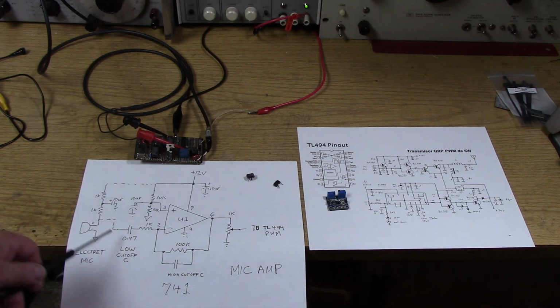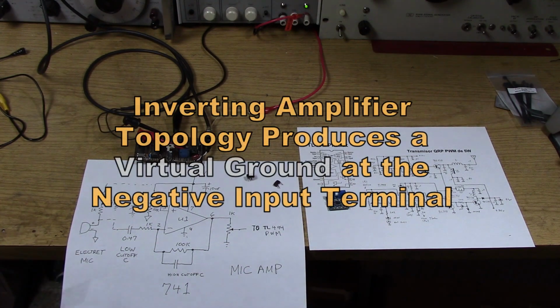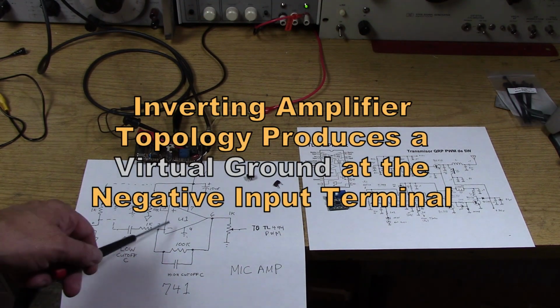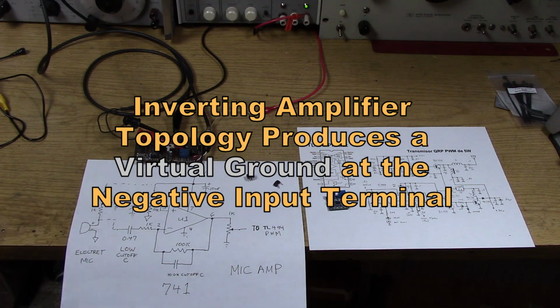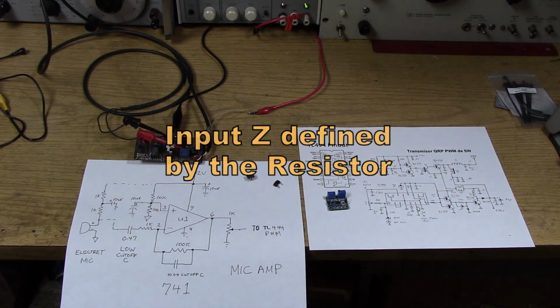I've got two capacitors that we can play with. We have the input coupling capacitor. The input is defined by the 1K resistor. This is a virtual ground, so it's exactly a 1K input on this op-amp.